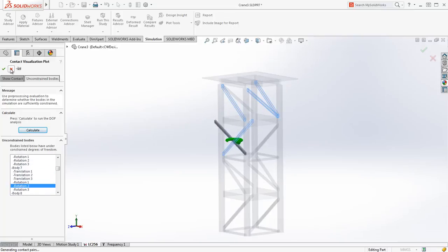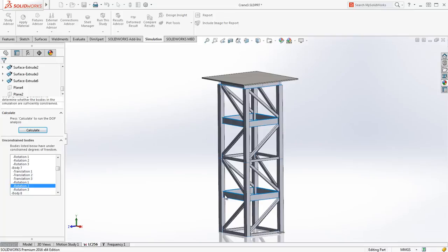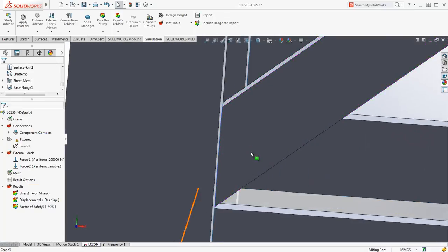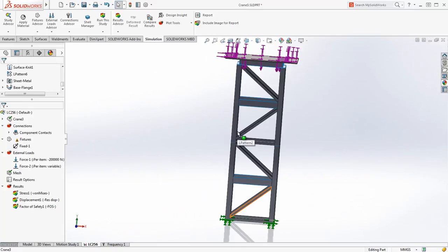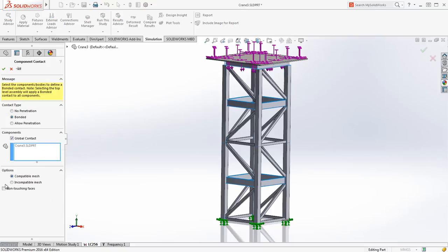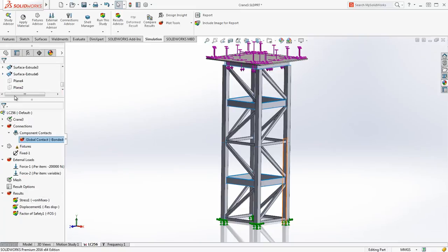The reason for that is there are weld gaps accounted for in the part design to account for tolerances. To account for this in the contact definition, you now have the new option to automatically account for edge shell bonding within a certain gap size. Activating these settings allows the model to solve without any problems.